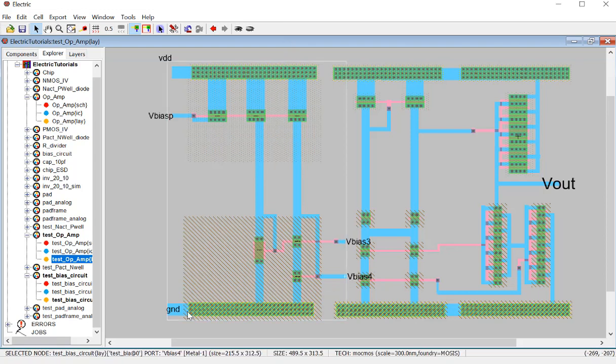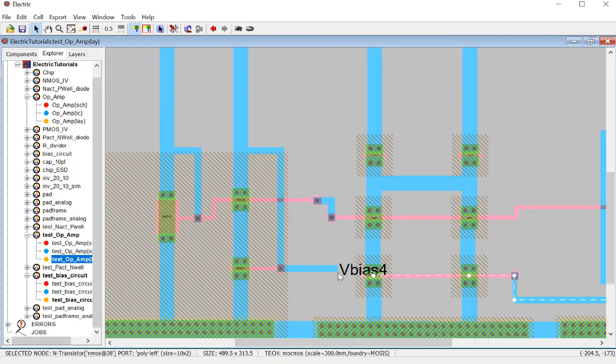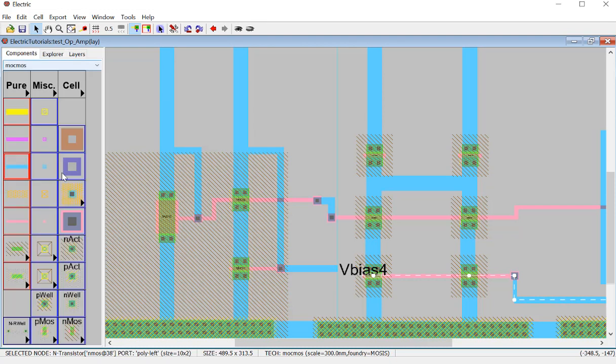So here's a node. I want to short it here, and that's this guy, right? And VBIAS P should be shorted to... It's not biasing anything over here, but this VBIAS 3 definitely is doing something. So this is how we connect that and pick up. You just do a left click and right click at the destination. It's going to directly do that connector for you. But this is too close. So sometimes the automatic method is not ideal, so you want to do it yourself sometimes.